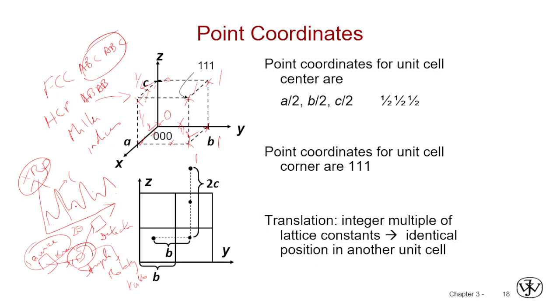Of this, we will find the prominent peaks, and from those prominent peaks we can find out at which particular plane the X-rays bounced off, right? Whether it is the 100 plane or the 111 plane, and from that we will be able to conclude which material it is. So you get my point, right? If we know the Miller indices of a particular material, we will know what that particular material is.